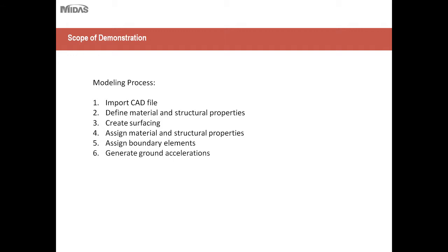And then we'll generate our ground accelerations using a database that's available to us in the program itself. I explained how all of these time history records are available to you. They're a matter of public record. Something really unique and powerful about SoilWorks is that all the records are available within the program itself, so you don't have to look into any outside sources.